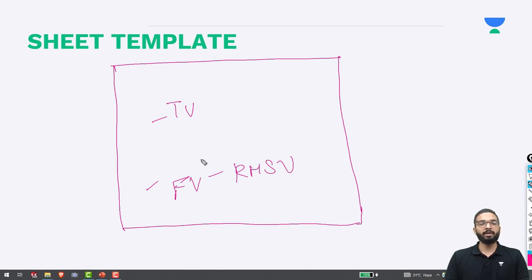When you are creating a lot of 2D drawings, it is an unnecessary waste of time to create all the sheet format details again. So you simply create your sheet format and sheet template and save them on your computer. Every time you create a new drawing, you simply load it and then start with your drawing itself. Now let's move to SolidWorks and take a look at how we create both of these.